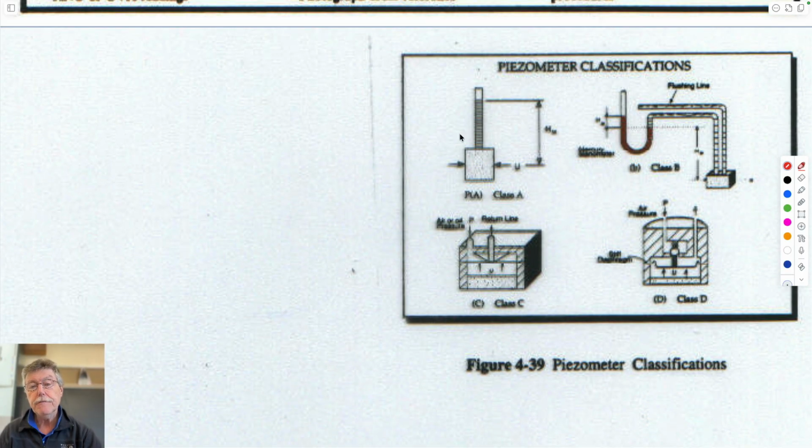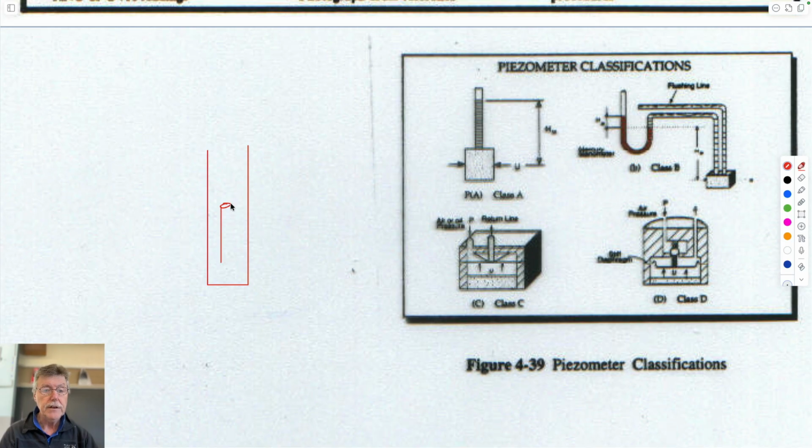If you've got extra data from your hole by putting piezometers in it, this standpipe piezometer, you can also put dedicated piezometers in it. So you could imagine within the borehole, if you wanted to, you could just drop a pressure transducer in there. Pressure transducer would be the size of your finger. It would go down here.